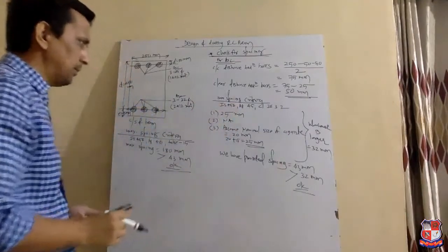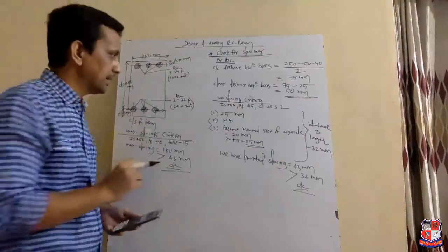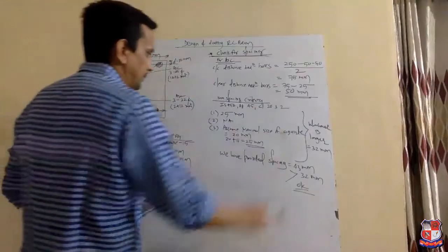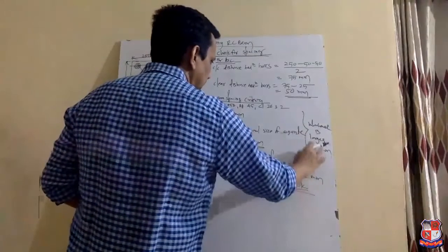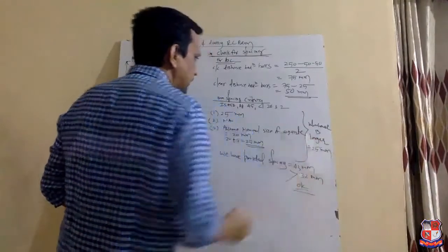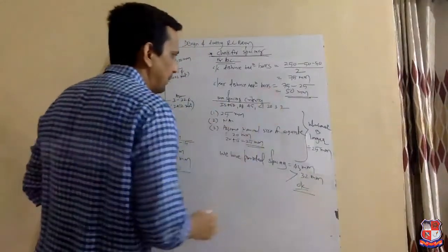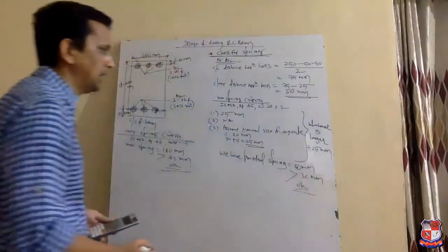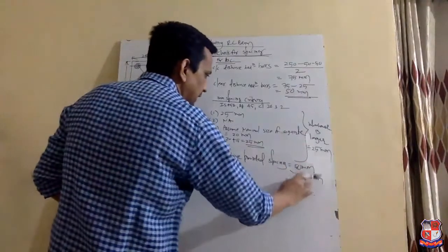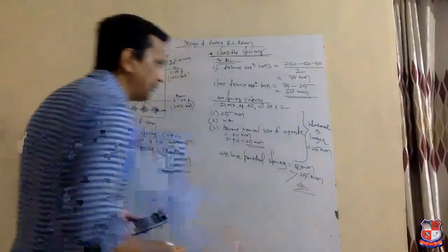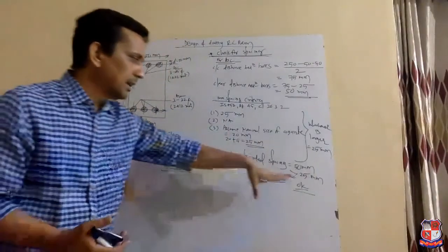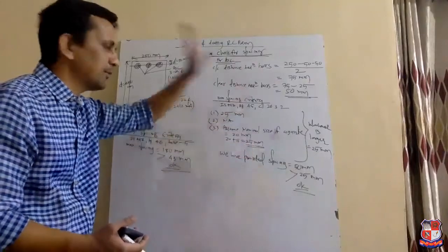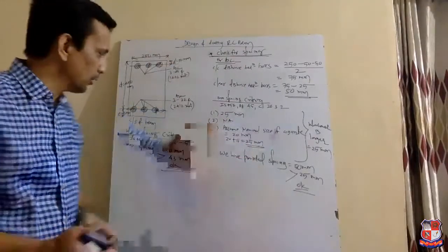Okay. So the diameter of the bar is 25 mm. The second criterion is not applicable because we have provided equal diameters, and the third criterion remains the same, 25 mm. Whichever is larger is 25 mm. And we have provided a spacing of 50 mm, which is greater than 25 mm. That's why our reinforcement detail satisfies the minimum spacing criteria as per IS 456.